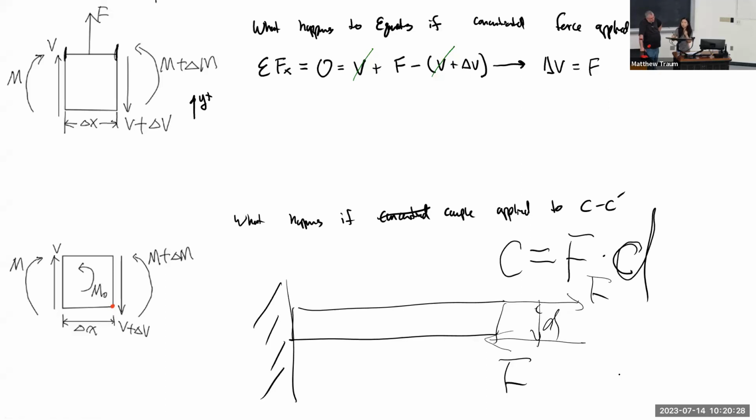But actually, in this situation, it is a bending moment equivalent couple like this. Understand? So a couple normally means an externally applied force on your structure. When we talk about the bending moment, it's normally the internal force, generated by the external force applied. It can be generated by a transverse force. It can be generated by a bending moment, by a couple.